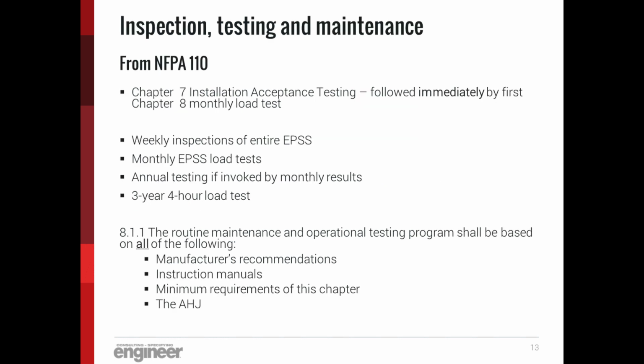So from NFPA 110, there's something that is important. Chapter 7 has the requirement on installation acceptance testing. When the installation acceptance test, which is quite substantial, and not everyone understands it, is completed, the 110 requirement is that it be followed immediately by the first monthly load test that's required by Chapter 8. You can't not do the first load test. The first load test starts as soon as the installation acceptance test is completed.